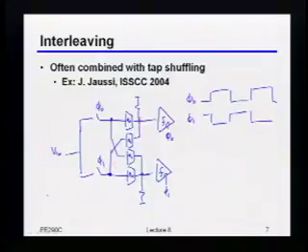That's a great question. So it strongly depends on how you're basically setting these coefficients in the first place. So you can imagine if I have an adaptive algorithm that's going to be controlling these coefficients anyways, as long as I can control those 2 independently, and I can get error information from both of them independently, I may not really care that they're physically 2 different structures. But if my adaptation algorithm can't tell the difference, meaning it can only give me 1 piece of error information, then you'd really have to make sure that they match sufficiently precisely. So that's another thing that we'll talk a little bit more about, which is that depending upon how exactly this is done, it may be fairly easy to guarantee that matching, or it may actually be quite challenging.